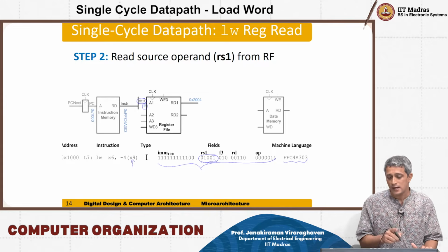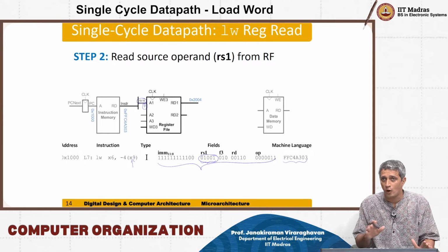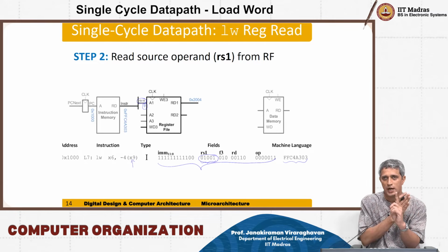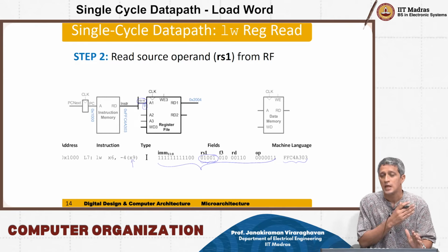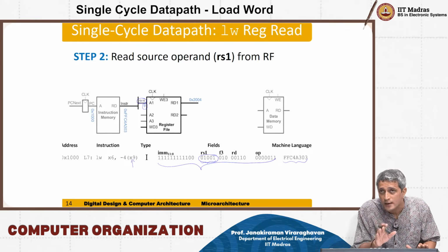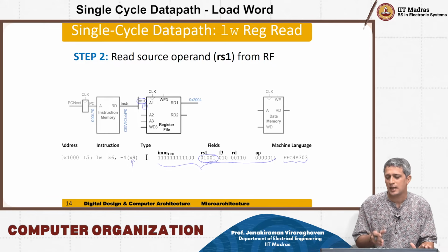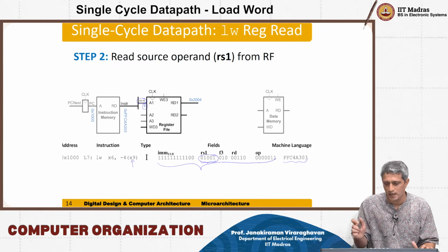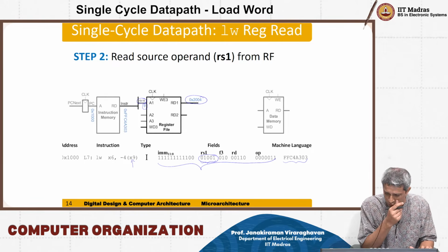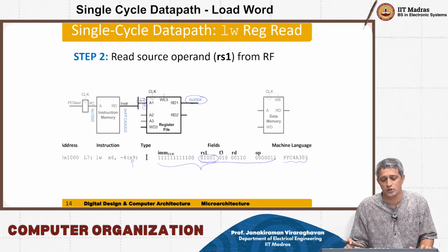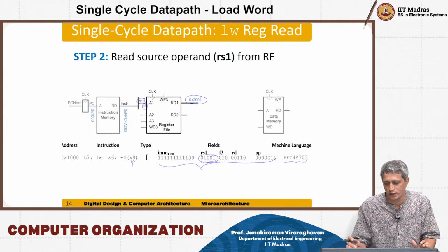Okay, and then again here remember the clock is not needed anymore. We needed the clock to pulse only once so that the program counter could latch that data, the PC next, and then start reading it. After that the clock is technically not needed. So you're going to take this A1 address, and then the data after a combinational delay will be available at this point. What is that data? It happens to be some 0x2004. That register X9 happened to contain this data 0x2004.